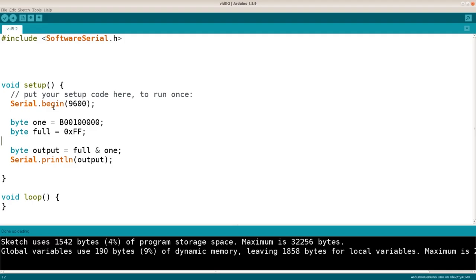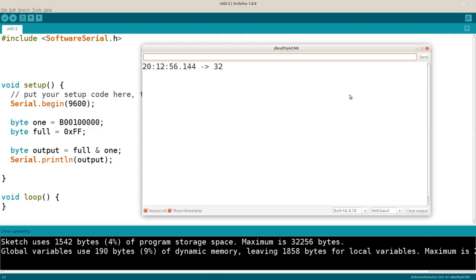Now it has compiled, so one always gets tricked by this difference of types. Now I've got the ending, which is a different value, 32, that means the position 5. So the bit at position 5 is set to 1. Why is this interesting? This is interesting because sometimes you have a port or register of 8 pins, and then you only want to get the input on one of these pins and manipulate the value, or sometimes the sensors will send a control signal or a start signal before they send the actual data, and you have to do this kind of manipulation by hand.